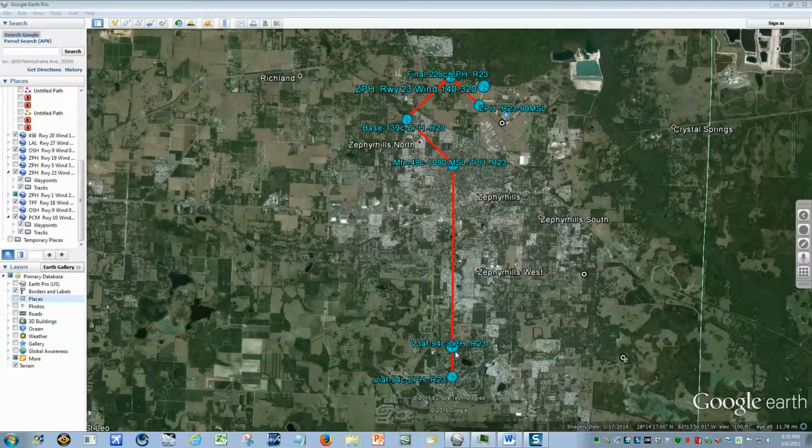We can generally select an arrival altitude that is 1,000 feet above the traffic pattern altitude at the V3AF waypoint, which will allow us to descend for 2 minutes at a controlled descent rate of 500 feet per minute at 90 knots ground speed to arrive at the midfield entry waypoint at traffic pattern altitude.